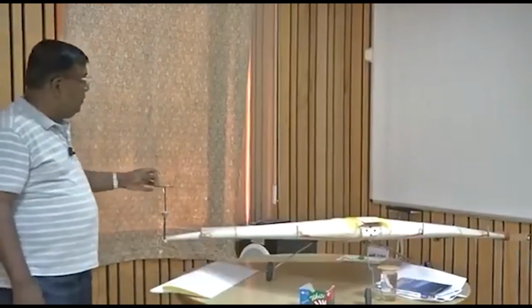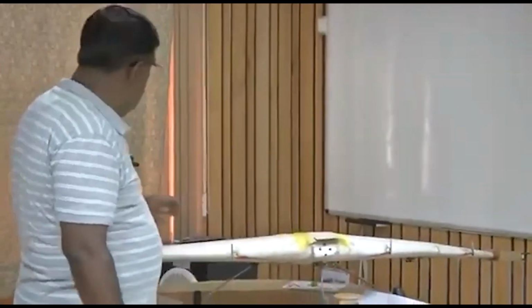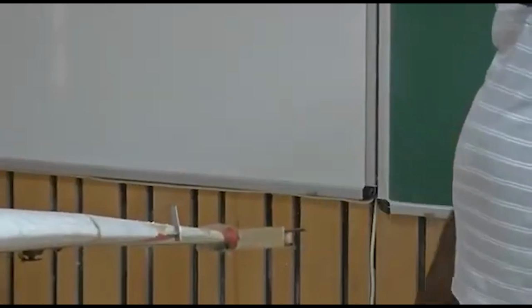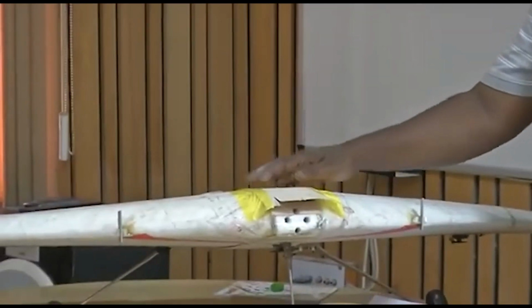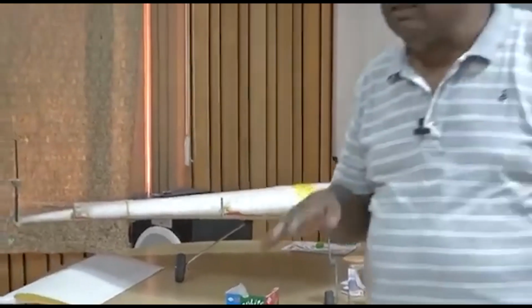Once we are sure through initial flight that these design parameters are okay, because in that model we also put instruments. We put the accelerometer, we put an angle of attack sensor. For example, if you see this delta wing model, here we have installed an angle of attack sensor and a beta sensor. The angle of attack sensor will be horizontal like this. It will measure angle of attack and beta. Sometimes for symmetry, we put the beta sensor, the sideslip angle or yaw angle sensor, here and the angle of attack sensor here, so that symmetry is not lost. We put an IMU, inertial measurement unit, inside this, which is gyro based, which tells you the attitude, accelerations, and the orientation through a magnetometer based instrument. Okay, these are extremely important.